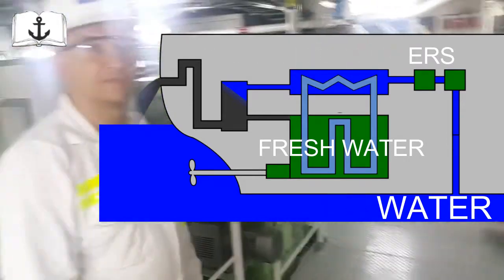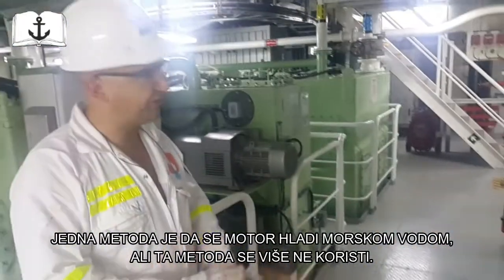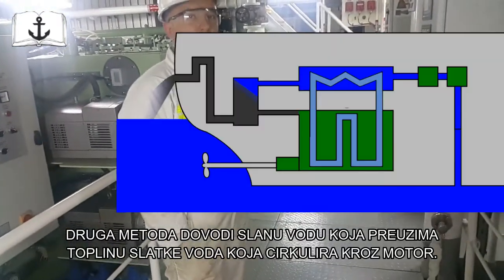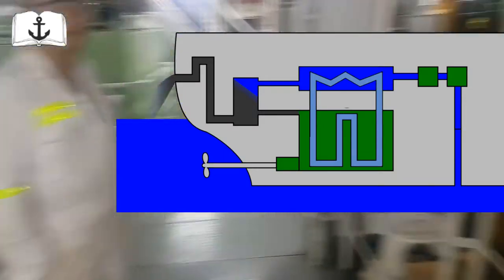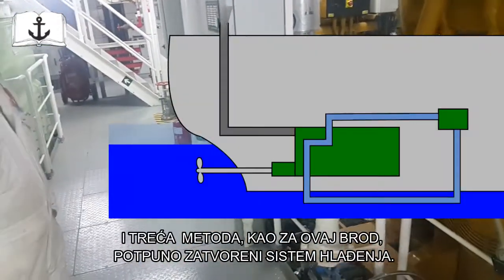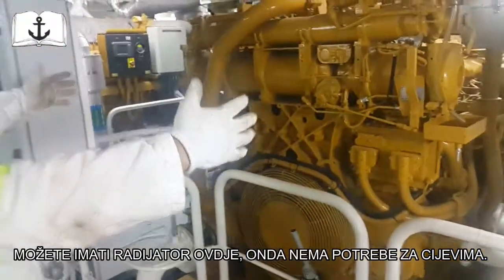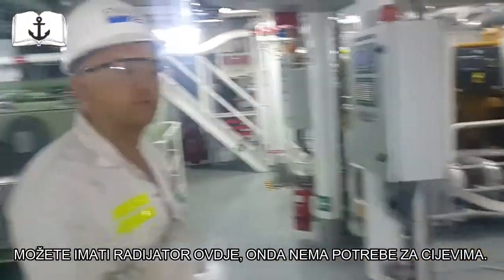So one way of doing it is conventional, where the seawater is going through the engine and cooling it, but that is finished now. Then a bit more advanced system is when you have seawater going through the heat exchanger, cooling down the fresh water, which is going to the engine. And you have specialized systems for vessels like this, where you have a closed system which is circulating water. You might also have the radiator here, so you don't need any lines. Yeah, it's the same as we have on the emergency generator.